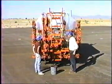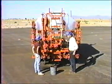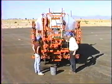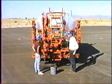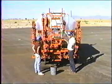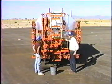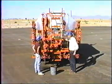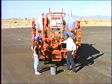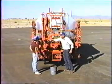Okay, we've hand sprayed, we've loaded it. There's several other pumping functions that we do with the piping back here that we'll briefly go over. Again, it's all just a matter of tracing it out, deciding where you want it to go and where you don't want it to go. Let's say that we come home from the job and we've got 1,000 gallons of material left in the tank, and we want to pump it back into our storage tank, and we want to use this pump. Okay, we're coming out of our tank, so we're coming out of the bottom of the tank into the intake strainer, in the bottom, out the top of the pump.